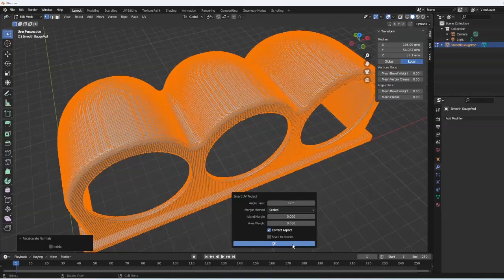Yeah, you click that. I'm not going to lie, this is getting more advanced and pushing the boundaries of what I know with mesh design tools. But with the island margin, we have to set this to some small value. It's usually between 0.02 and 0.05, because we're going to apply a texture to it that will have to repeat throughout this part. So this is going to help transition between edges, so we don't have obvious seams between the texture boundary.